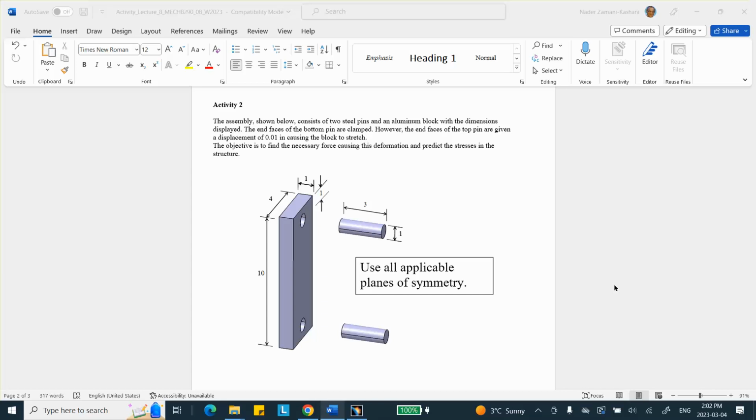Okay, so I'm going to do this through the top-down approach. In other words, within the product, I'll create all the parts, and then I'm going to split it. It is up to you whether you want to create only the portions of the model that are needed. If you know there are two planes of symmetry, you can start modeling based on those two planes of symmetry, or you can model the whole thing and then use a split in, for example, the product design to split these parts simultaneously. That's what I'm going to do.